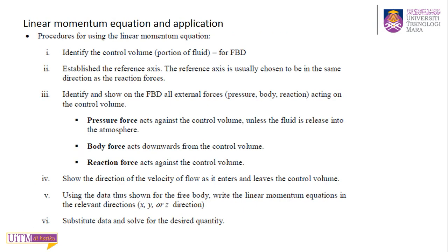Alright, we move on. Whenever you find a problem regarding the linear momentum equation, you can just follow this procedure one by one, step by step. In any problem, the easier way is always to follow step by step. First, you need to identify the control volume. In any question, they will give you a pipe or a pipe bend, so that's your control volume.